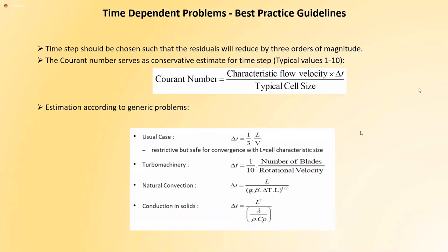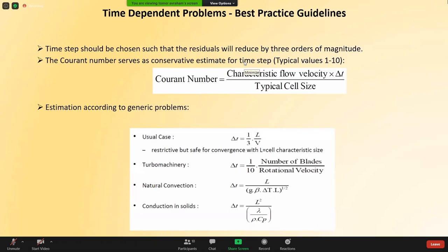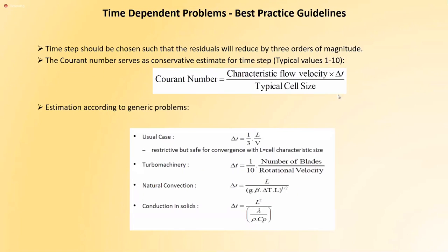Smeared across surfaces for explicitness, the CFL should be under 1, correct? It depends what you call it. It should be under 1 for a finite difference scheme, where everything is the same size.